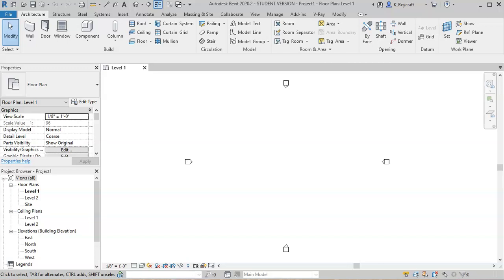All right, let's look at modeling floors in Revit. The Floor command is very easy to use, not very complicated as far as options are concerned. Basically, when we think about modeling floors, we have to think about elevation. Where do we want the floor created?